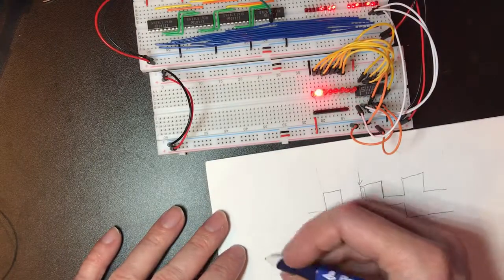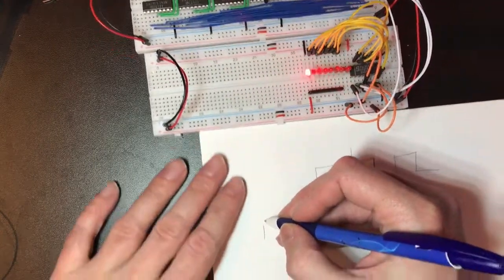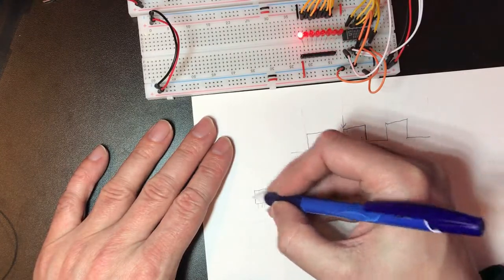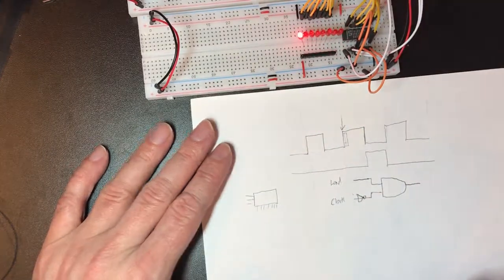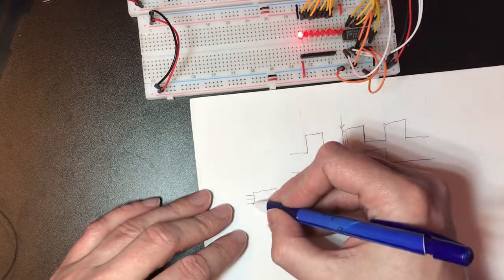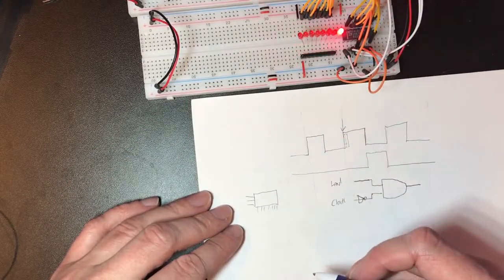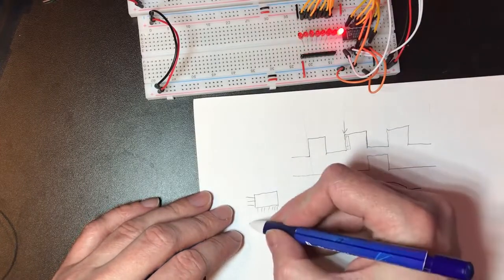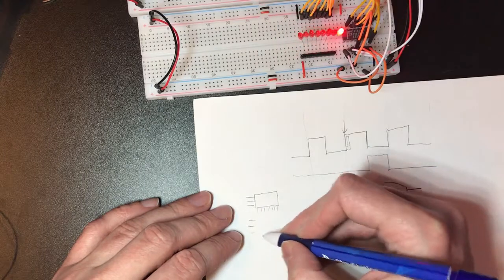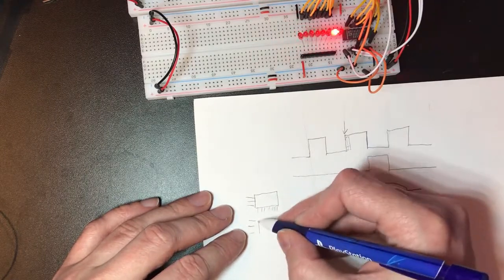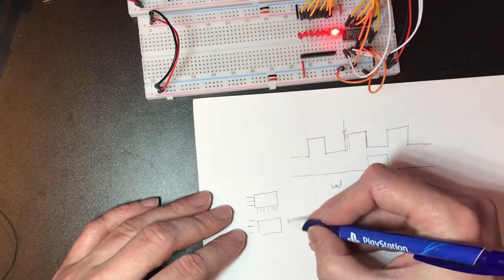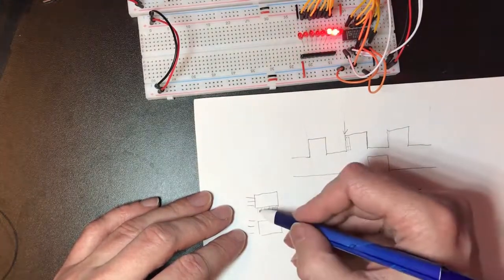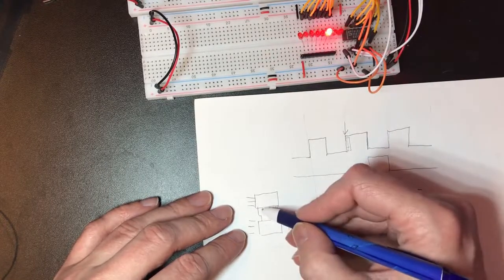So if we've got one of these chips, so we've got our 8 output lines and we've got our 3 input control lines, we could increase the number of outputs we have dramatically by having an additional 3 control lines, one of these chips here, and then 8 of these chips out here, with the outputs from here going into the enable lines of each of these.